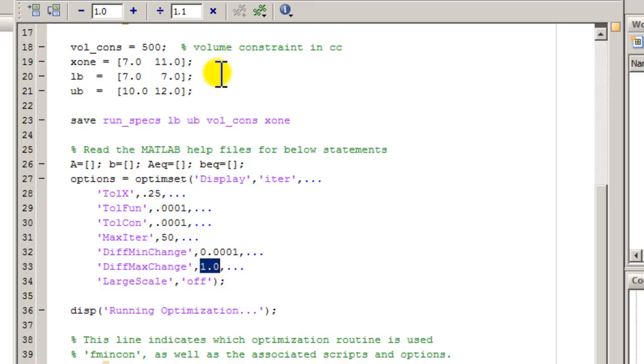From that gradient information, the optimizer calculates the constraint violations and the functions, and it uses derivatives to find out what the next set of x values is going to be. Then it continues from that point on until it reaches these termination or convergence criteria.